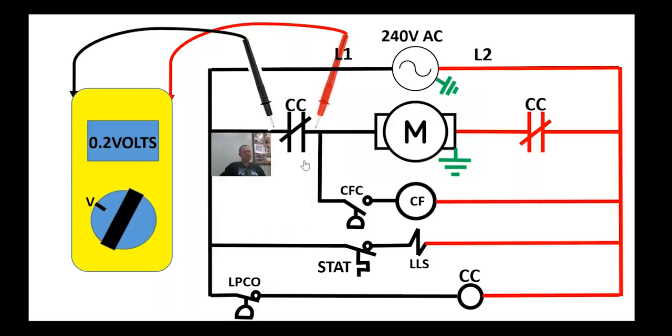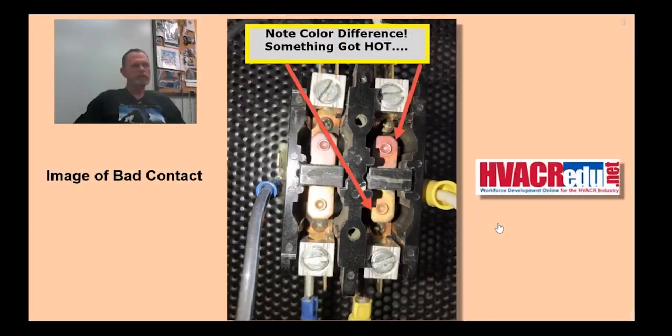But supposedly if I look at this switch, I've got a voltmeter going across it right now, I get 0.2 volts dropping through that switch. What should I have dropping through the switch? I should have nothing dropping through that switch. When I look at that switch with my voltmeter, I should see 0 volts. Now, here's the result of a voltage drop through a switch.